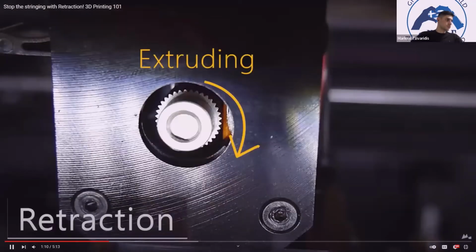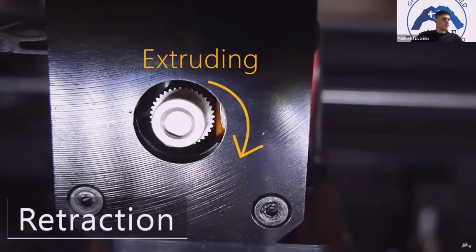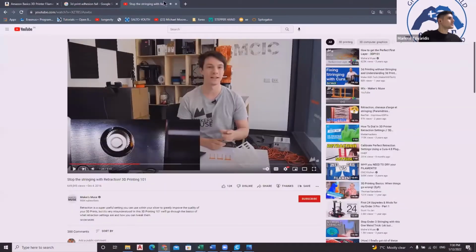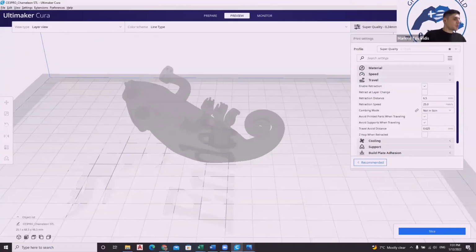Stop stringing. Well, this is called retraction. Retraction actually pulls filament back up from the hot end a short amount after each print move. There's actually a bit of a myth around retraction that it somehow creates a suction and sucks molten plastic back into the hot end. That's not actually the case. All retraction is doing is relieving that pressure when you do a travel move. So this is retraction, guys.